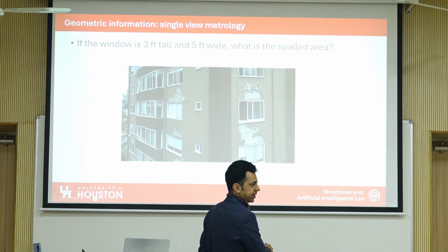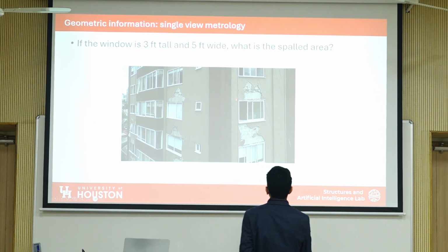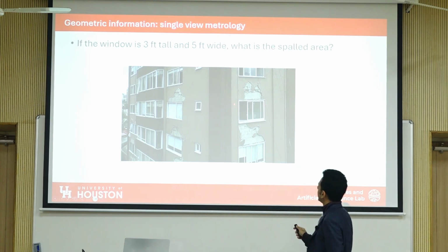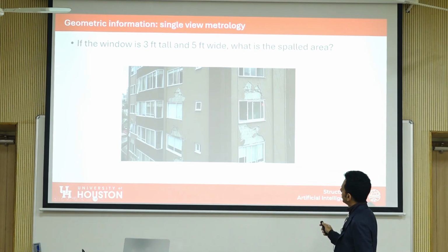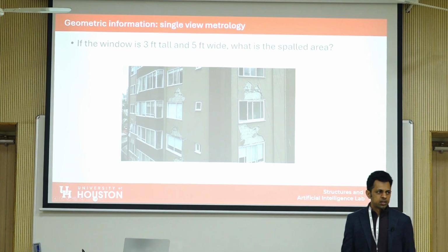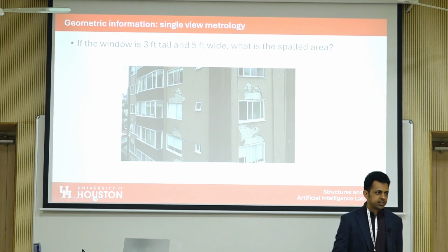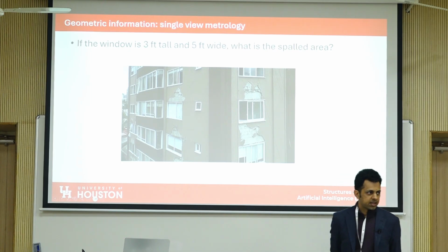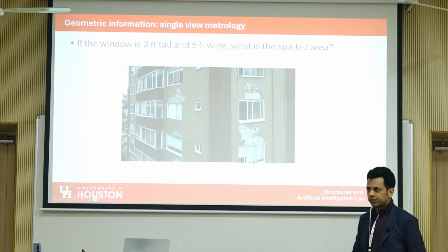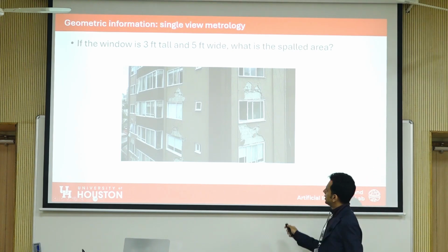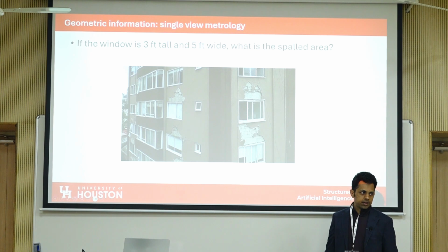Yeah, from the window you calculate the pixel length. If you know the width of this window and the height of this window, you can calculate how many pixels represent this window, the width and the height. And so you get some sort of scaling. Now, what is the complication that makes it not so trivial? It works for planar structures, but here this wall you can treat as a plane.